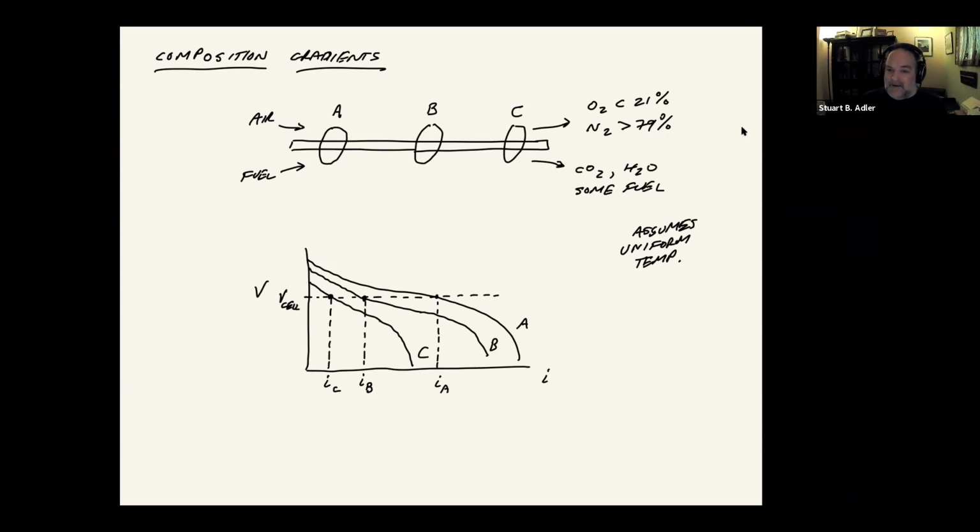So the reaction kinetics, the rate at which hydrogen can be oxidized at the anode, depend on the gas concentration. As the fuel concentration goes down, the kinetic rate coefficient for the reaction gets lower, which means that for the same cell voltage, you get less current density, or conversely, for the same current density, you have a higher overpotential to drive that current density that you're trying to drive. The net effect is that the polarization curve gets steeper, or you get more voltage loss for a given current density because the gas concentrations get lower.